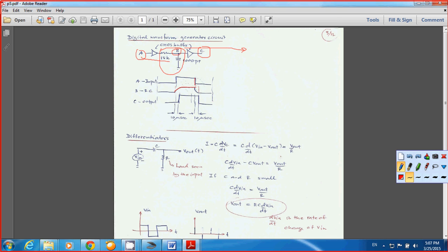And when you have no input coming in, your capacitor starts discharging, and it looks like that one. What happens is that this digital waveform generator circuit will delay your input signal like this one. Everything is going to be the same except it shifts your input signal by a certain amount of time. Look at this one, it shifts by 10 microseconds. Okay, so this just gives you an idea about what happens when you connect your RC circuit here between two CMOS buffers. You have your input voltage showing up at the output. It's just like a delayed signal or delayed digital signal. If you want to do that, you can apply this circuit.